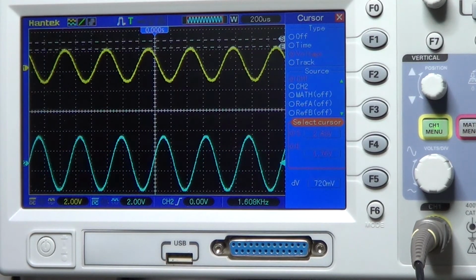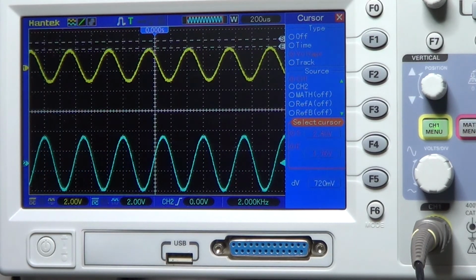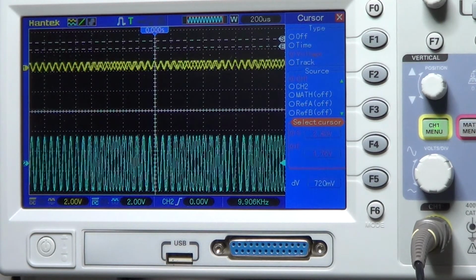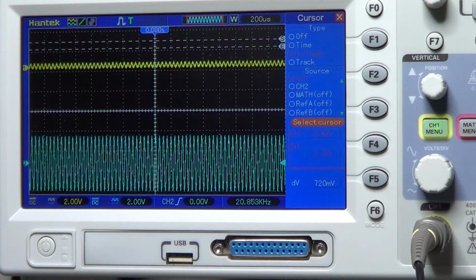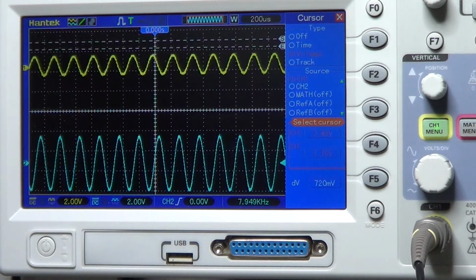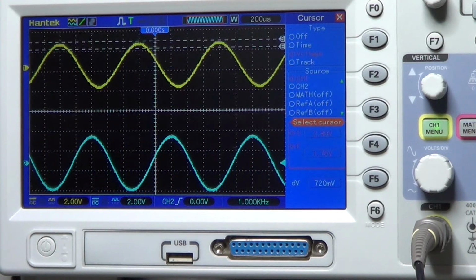If we now increase the frequency further, the amplitude of the output signal will become smaller and smaller at a faster pace, that of 20 dB per decade we mentioned previously. Decreasing the frequency, of course, will reduce the attenuation and the signal will increase in magnitude.